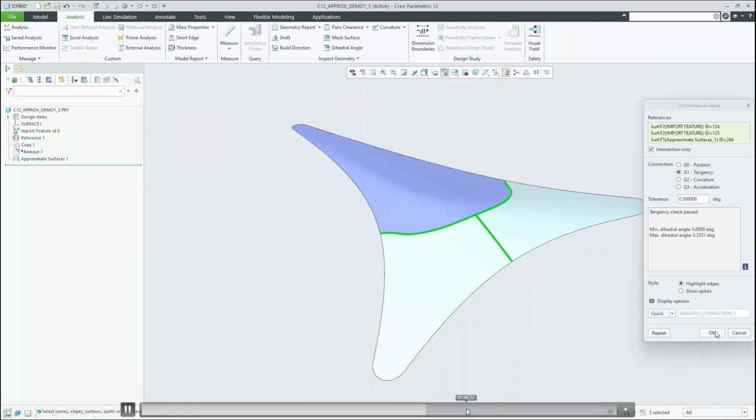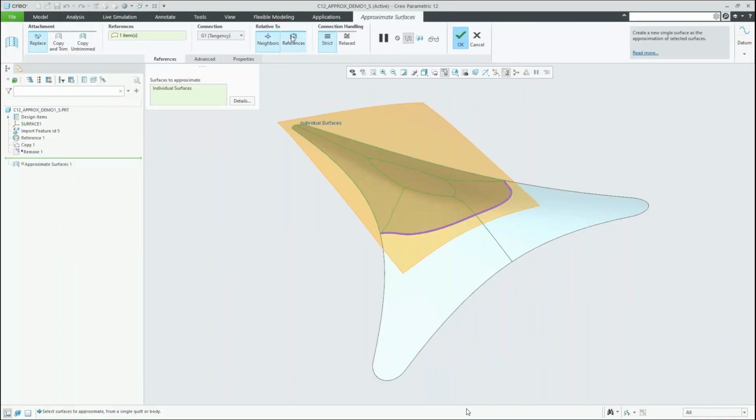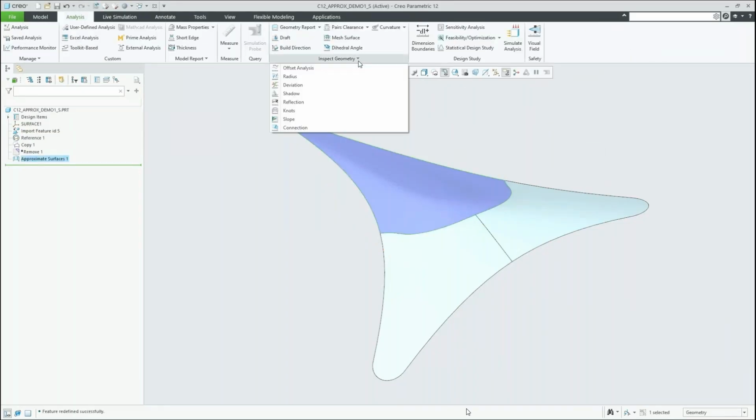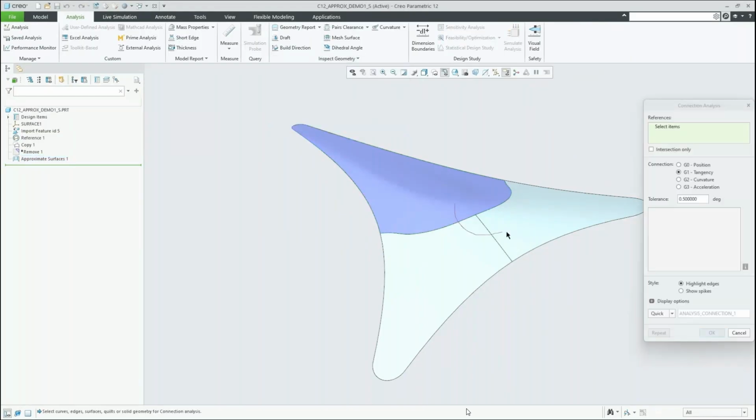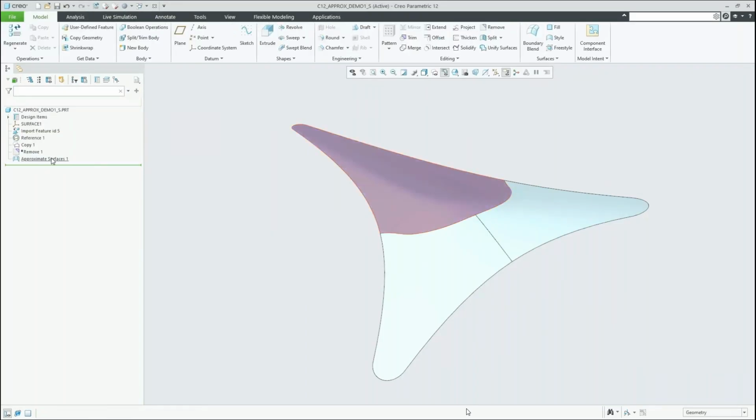So that's the first step that we do. And the second step, the second test, is changing that to the references. And then he looks to that outside as well to maybe change that surface. So this is, on the other hand, a little disadvantage. He will change, or Creo will change that surface a little bit in some cases. Not big. It's like with the curve, it's the same effect. If you have a curvature continuous, he will change the curve or the surface a little bit.